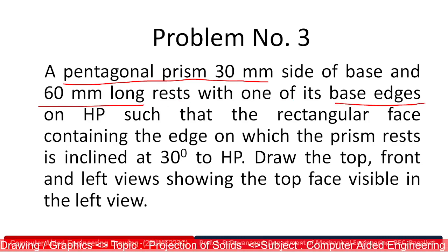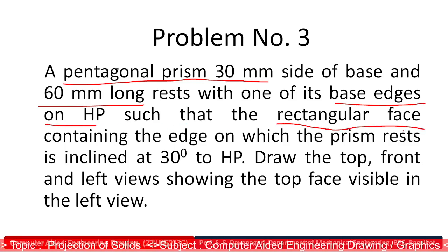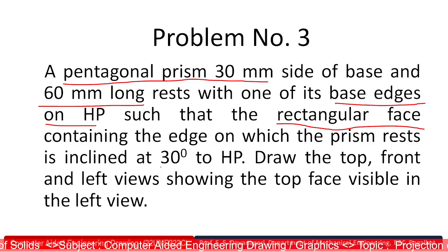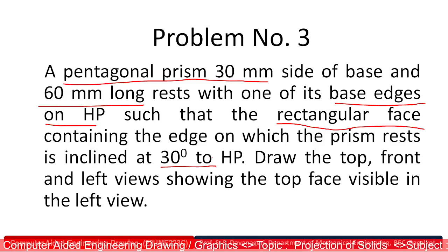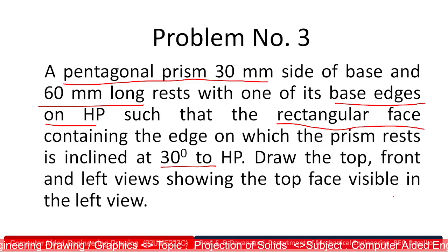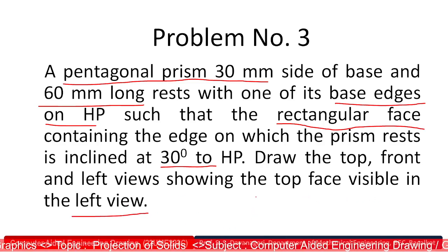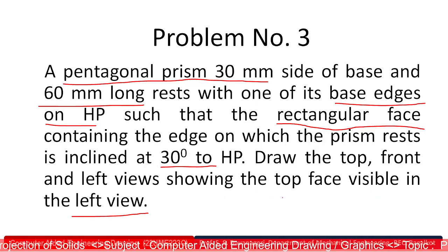of its base edges on HP, such that the rectangular face containing the edge on which the prism rests is inclined at 30 degrees to HP. Draw the front view, top view and left side view, showing the top face visible in the left view. So that means you need to draw the front view, top view as well as side view.